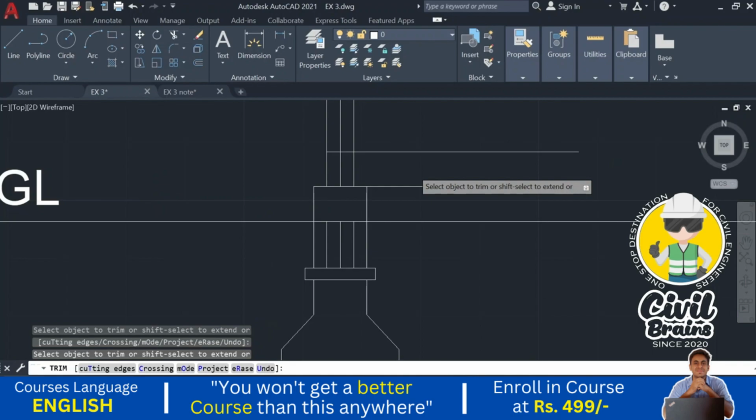So after the excavation, the next step is we need to provide the PCC. After setting out the PCC, next we need to provide the footing in the RCC structure. How do we need to provide the footing? So what is the footing? It is an RCC structure, that is reinforced cement concrete. Below that we have provided the mesh. Okay, the steel mesh we need to provide.